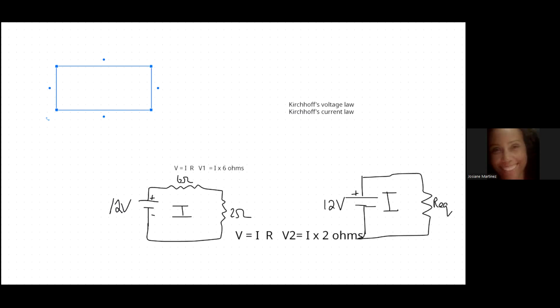Okay? Notice that is a lot lower than the last scenario with the parallel branches. We had, how much current, wasn't it? 8 amps? Was quite a bit, wasn't it? Now the power through each element, you just take the current flowing through it times the voltage across it, right? And since we know the current and the resistor, why don't we use the form of the Joule's law that only uses current and resistance?